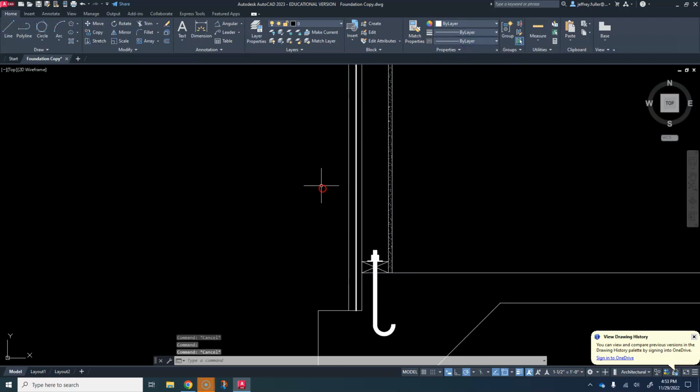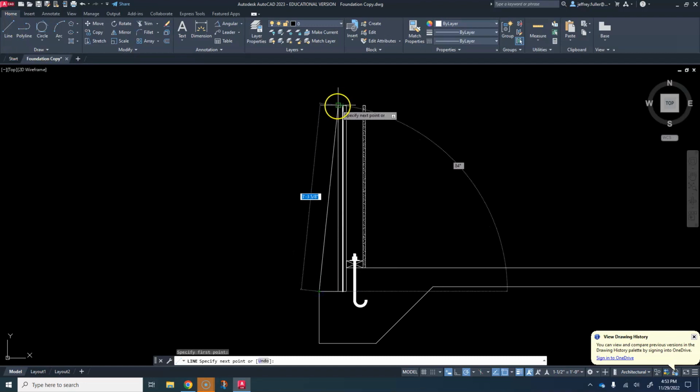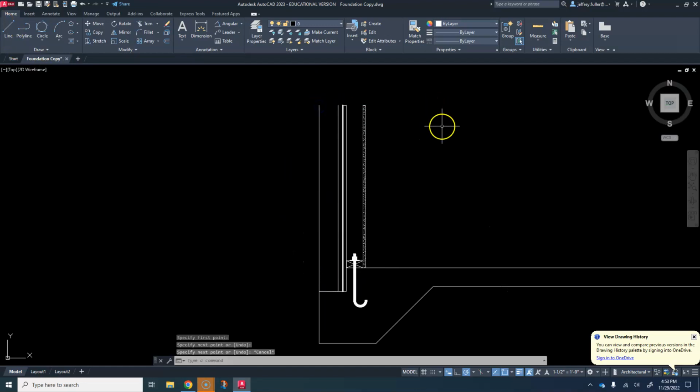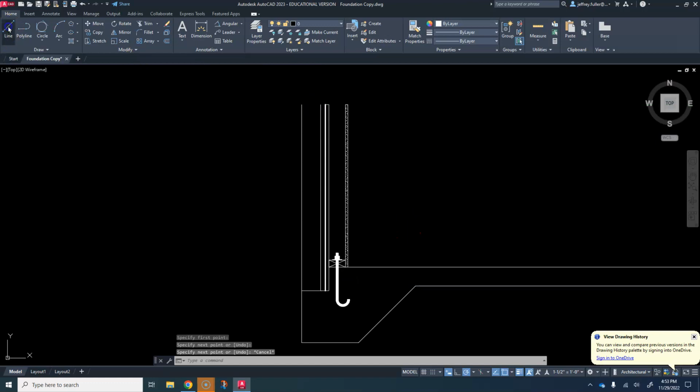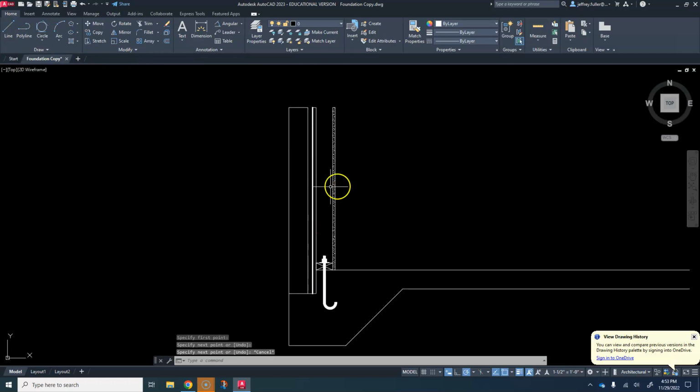Now I'm almost done with my wall material. That is my airspace, as I said, but over here I've got bricks. So I need to draw a line. I'm just going to draw a straight line with the line tool right here from this corner, straight up, match it up with the top of that line right there, and go ahead and cap it. I should have capped it while I was there. Cap it off, and now we're going to put another hatching inside of it.